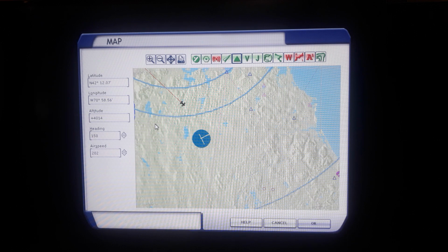So it is also fail safe. Okay, now this is Benin, I am glad I got it back. Now we will come here and intercept this at around 10 degrees. This is 330. So for a 30 or 40 degree intercept angle, it will be 10.